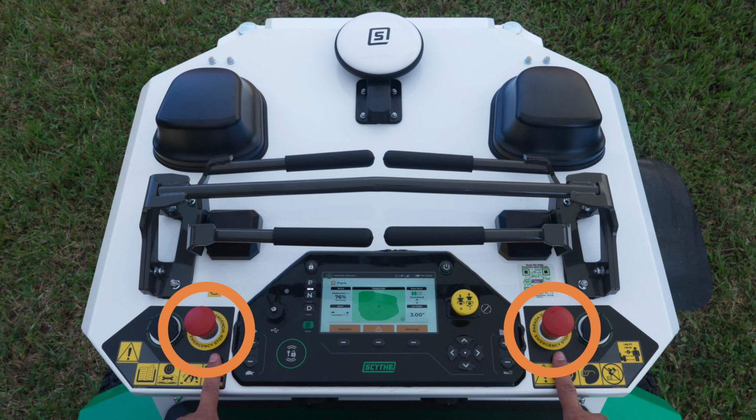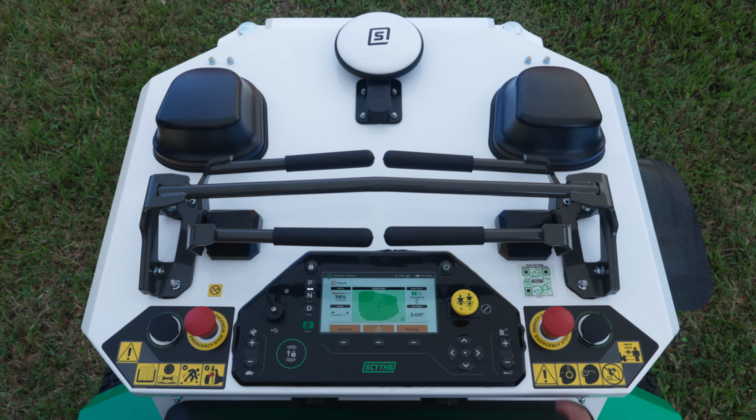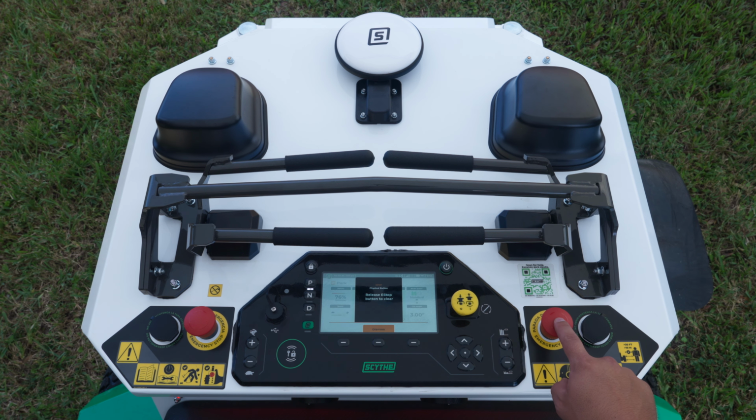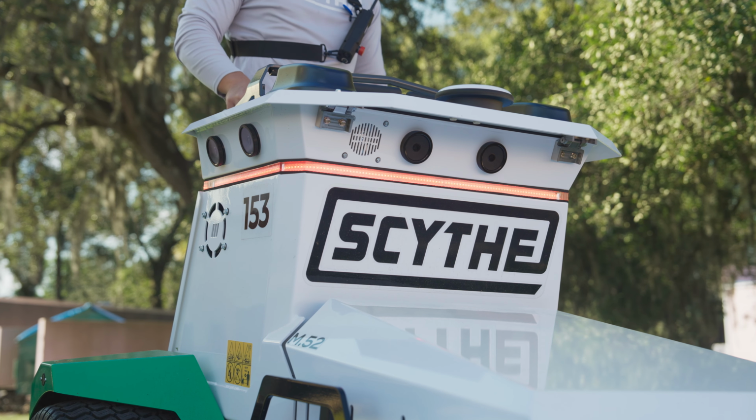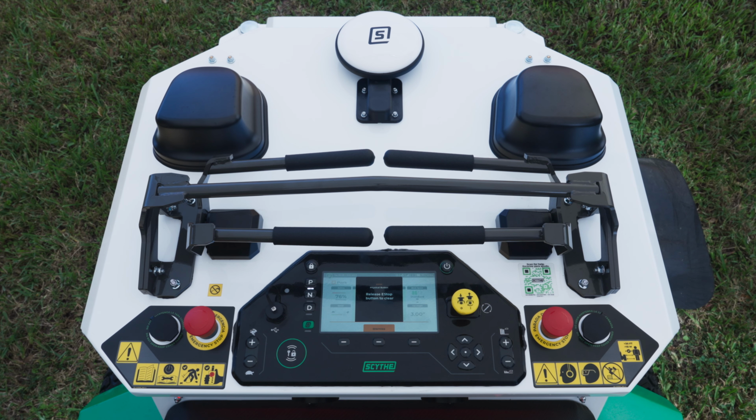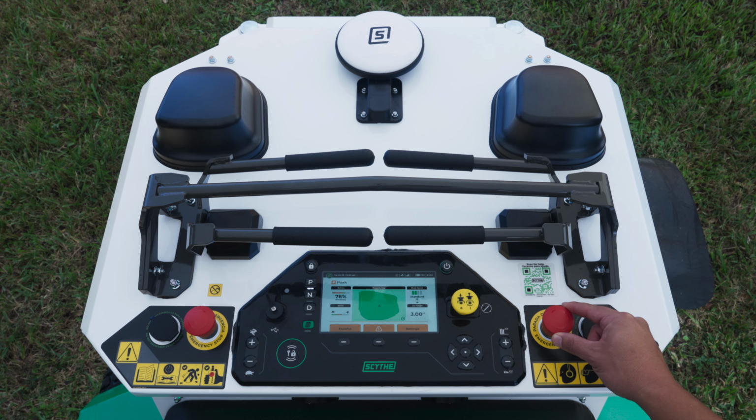There are 2 onboard emergency stop buttons, or e-stops, on your M.52, 1 each on the left and right side. Engaging either of these e-stops will bring M.52 to a rapid stop. The blades will stop and the blades will become unpowered. Note: the machine remains powered on when the e-stop is engaged. The light bar will become a solid red to indicate that the e-stop was engaged. To release the e-stop, slightly twist upwards in the direction of the e-stop button arrows.